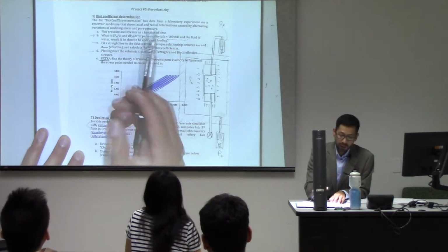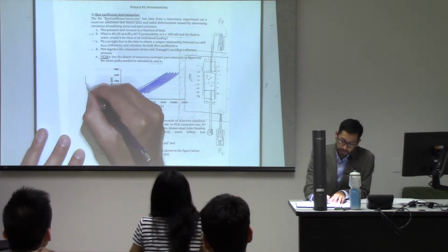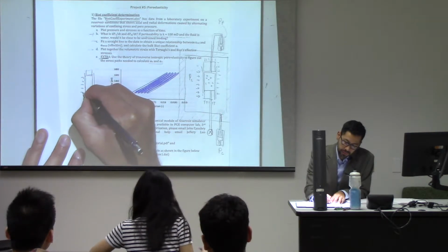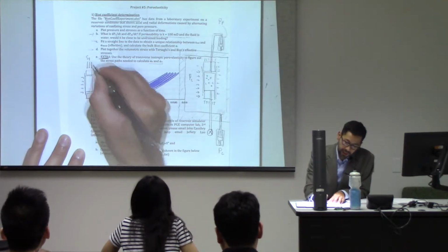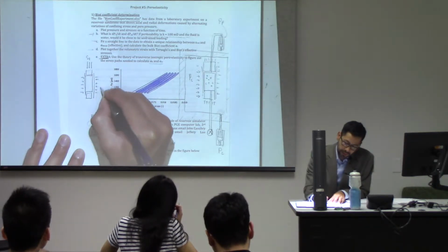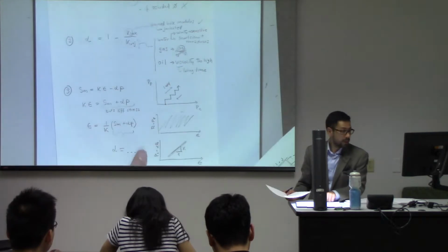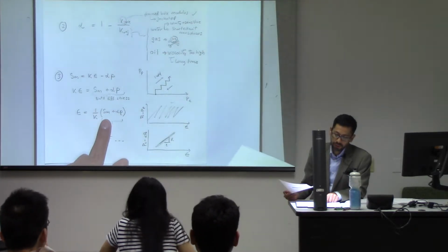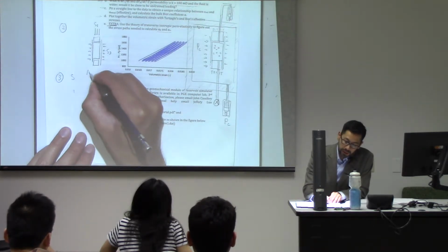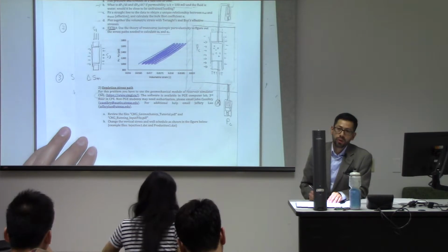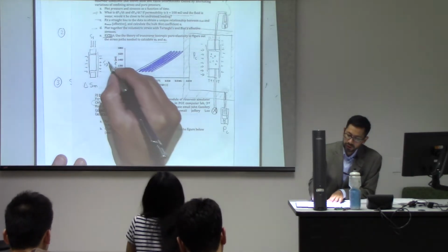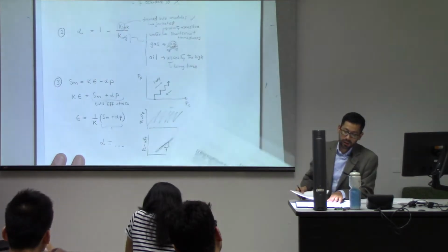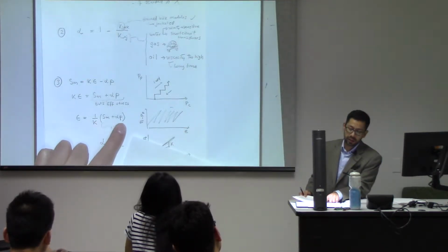In the actual experiment that you have over here, your S1 is different than your S3. You're going to have S1, and here you're going to have S3. In this equation, in order to get K, the only thing you have to do is evaluate the change in mean stress. When you increase the confining pressure, you change S1 and S3 simultaneously by the same amount. So when you take the changes of the mean stress, that is what is going to go in here. Here there is going to be a change, and here there is going to be a change too.